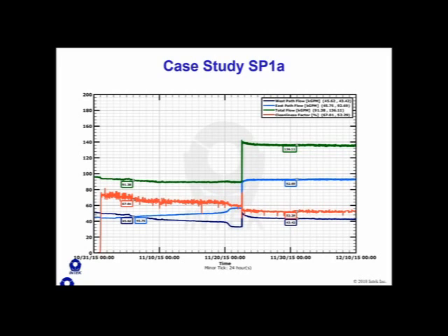It is just using the formula to calculate the measured heat transfer coefficient over the ideal HEI heat transfer coefficient. That's really what cleanliness factor is. It's your measured heat transfer coefficient divided by the model: good flow rate, good inlet temperature, good tube material, good clean tube, divided by that determined heat transfer coefficient. So it has nothing to do with a random factor. It's just straight out of the formulas that I showed yesterday.